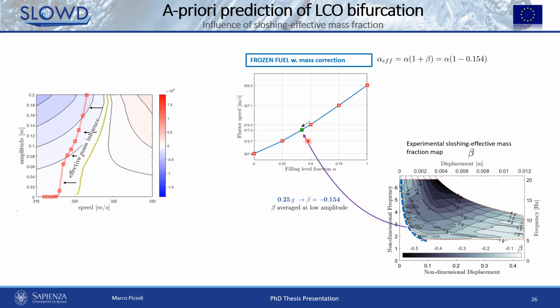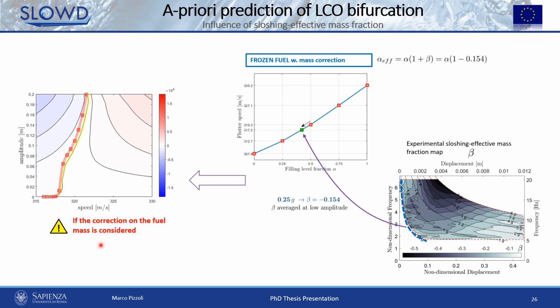And this results, in terms of energy, in obtaining a map in which the zero energy line, so the yellow line, is superimposed on the bifurcation diagram found from the gust response analysis, as we can see from this map. So the identified reduced order model can faithfully reproduce the behavior of vertical sloshing even when integrated into a complex aeroelastic system such as the prototype commercial wing.